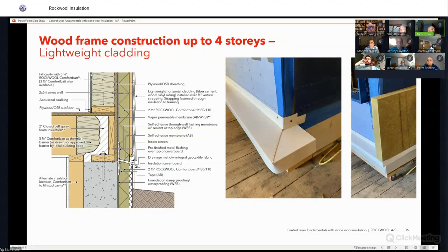And again, having a vapor control layer at this location is something that I highly recommend, but not using poly. I really am a big fan of using them with adhesive. So basically my top plates, my bottom plates, my walls, putting a bead of adhesive all around.